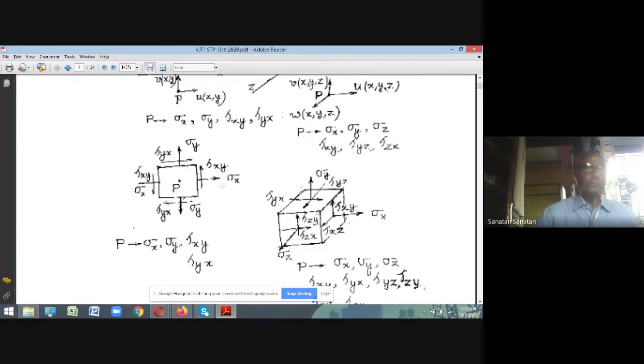You see, that is the point, and then how do you actually show these stresses? Generally, to represent the stress state at a point, we consider an infinitesimal square enclosing the point P, and this square has four faces. You see that this face, which is on the right vertical face, is actually called the x face. Its outer normal is directed in the x direction. That's why it is indicated by x face.